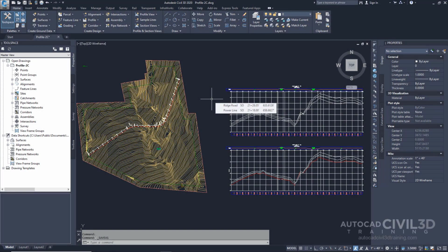In this exercise, you'll create the layout profile. Typically, the profile is used to show elevations along a proposed road surface or a finished grade. The layout profile is similar to a horizontal alignment in that it's constructed of straight tangents with optional curves placed where the tangents intersect. These tangents and curves on a layout profile are located on the vertical plane, and the intersection points are called points of vertical intersection, or PVI.